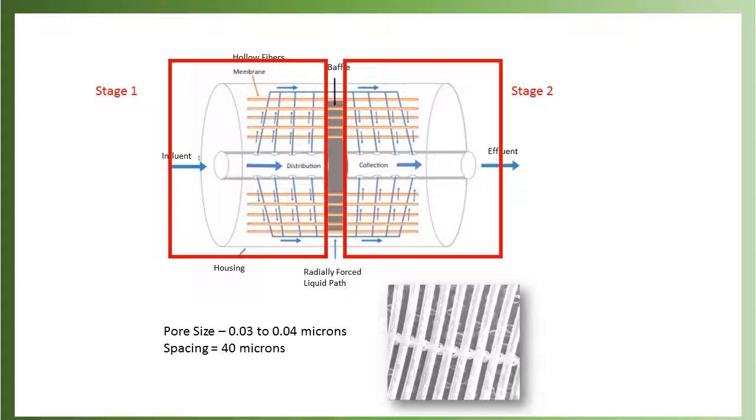and this thing ran for months. And so while fouling can be a problem, we haven't seen it, at least on the liquid-liquid side, with these, because the spacing is large and the pores are pretty big. So, and it is in these pores where you're getting the mass transfer. So that's where your liquid film is to get that mass transfer.